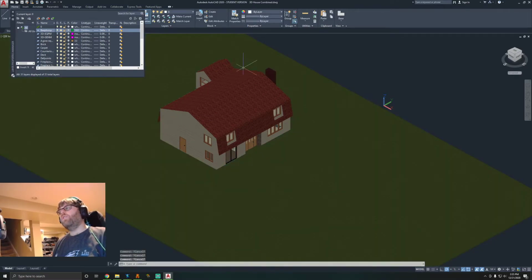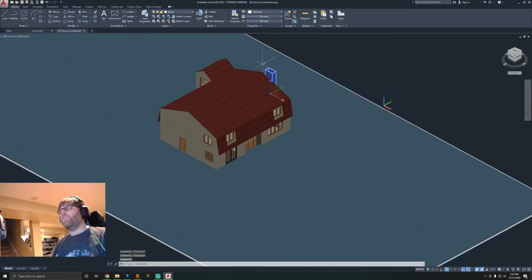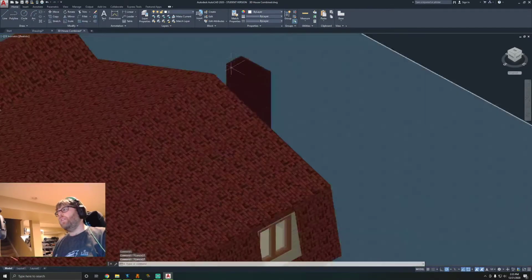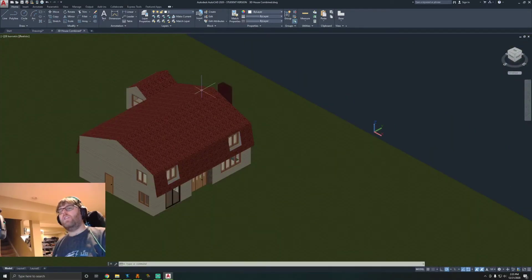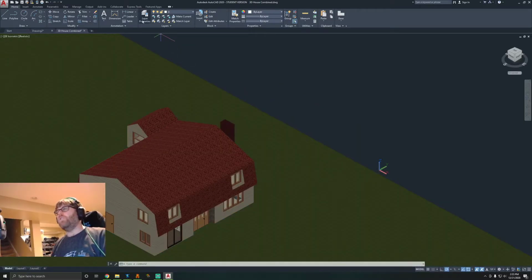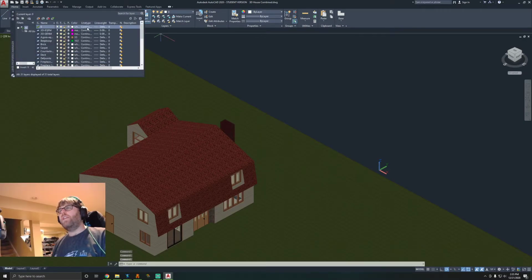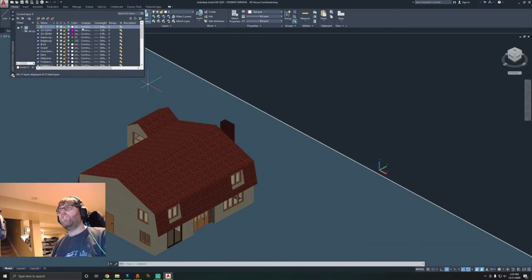What you could end up doing is click on an object you drew. Right now I have that set to brick, so it ends up being this brick material, which we'll get into in the 3D version of this presentation. But right now, if you wanted to change colors or line types or stuff like that, you could do that in here. So if we wanted to change the line type, we could load in a different line type. Say we wanted it to be this long, short, long type business. You could end up loading in that line type and changing.